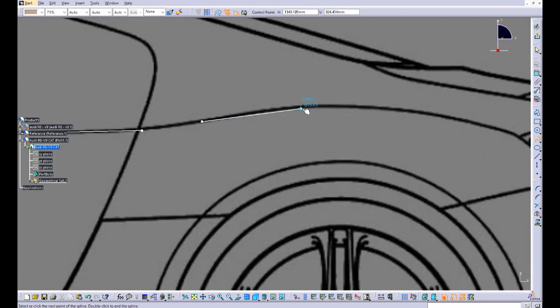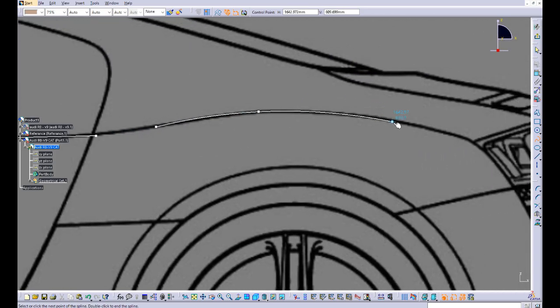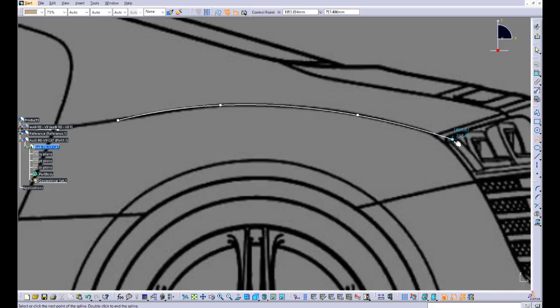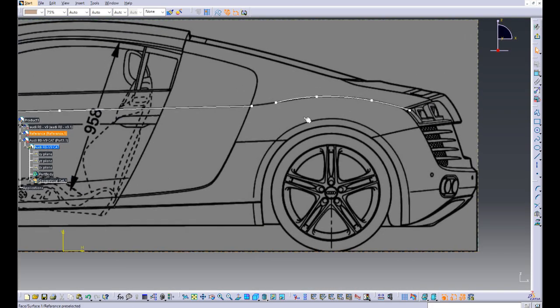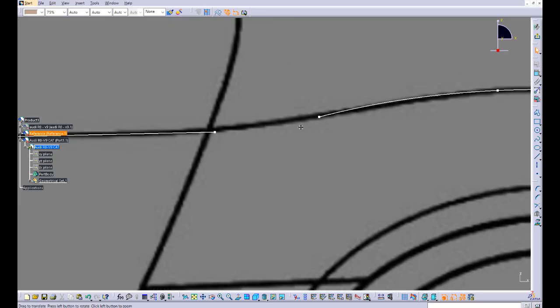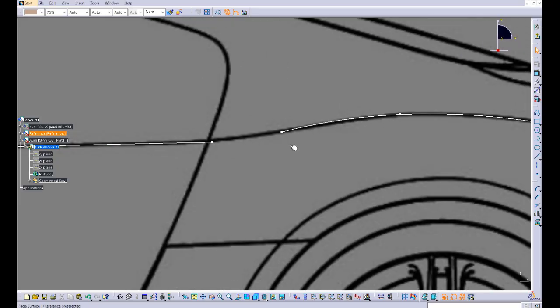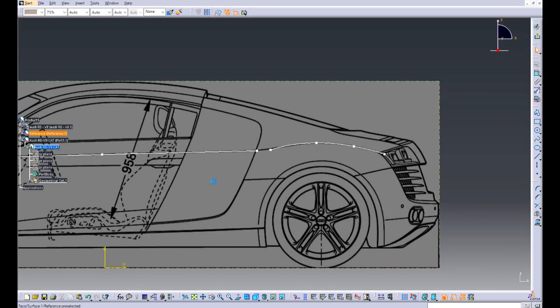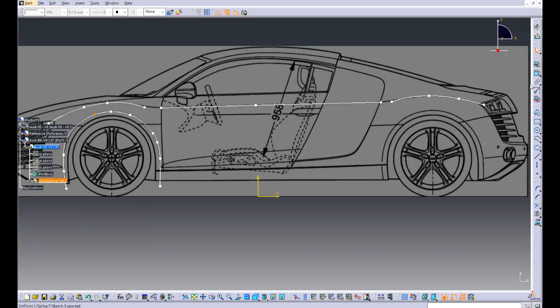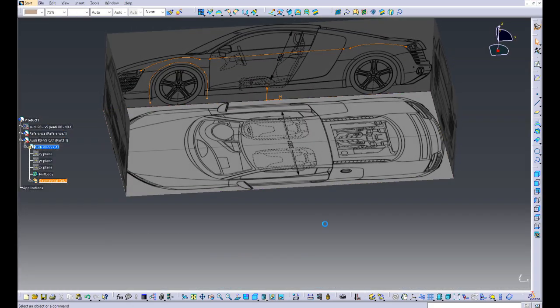I hope you have already set up your reference image and are following along with me. I generally use 3 to 4 point splines at maximum, so you can skip the small transitions that we can achieve by the blend command later.